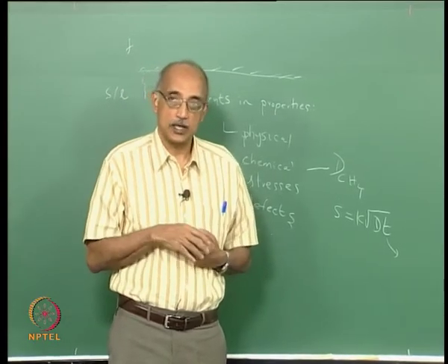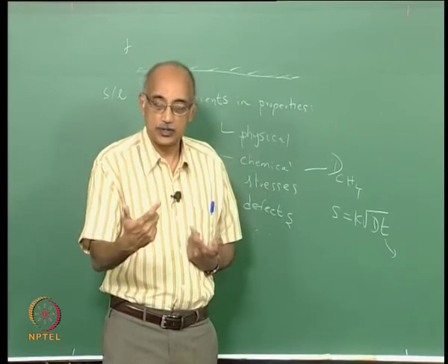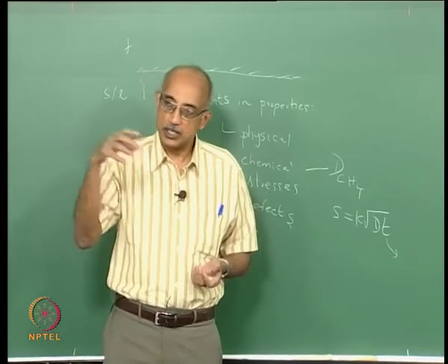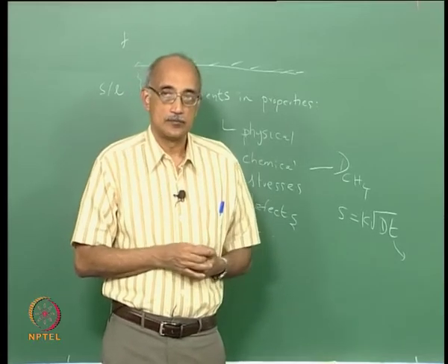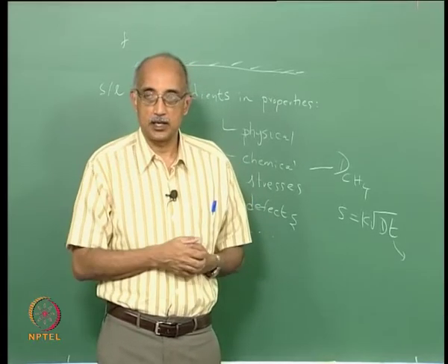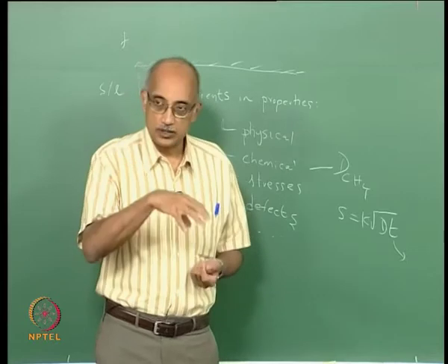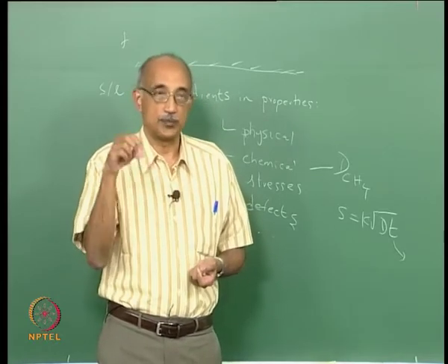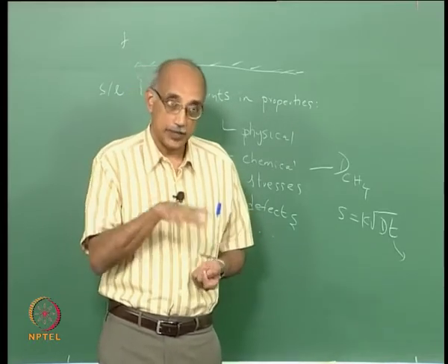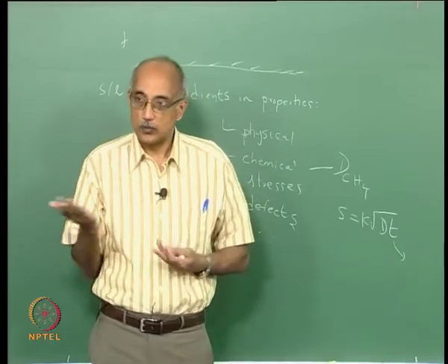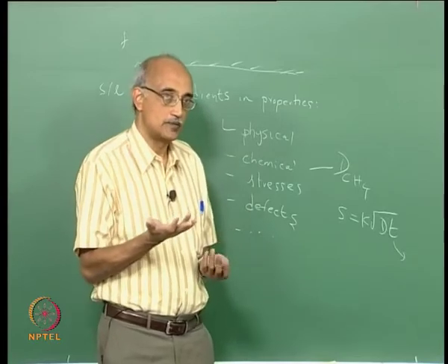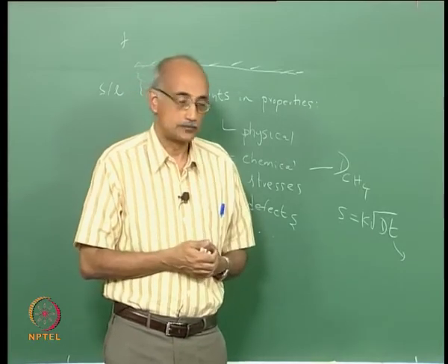However, you can change its external surface to aluminum oxide, and you can change as much of the subsurface as you want to aluminum oxide by providing a diffusion path and by controlling the concentration of the diffusing material, the pressure that you are applying, the temperature at which you are applying, and most importantly the time for which you are exposing that material to the diffusing species.